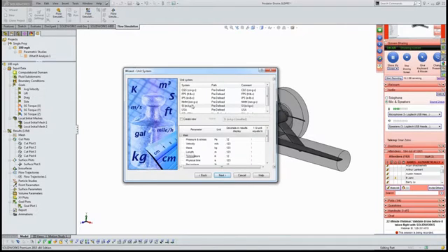Now the next thing that it asks, all right, what unit system do you want to use? And for those of us that are based here in the U.S., you know that we're very tied to our U.S. unit system. We're not a huge fan of metric. I'm not quite sure why, but that's the way it is. So I'm going to use the SI unit system, but I'm going to make a couple changes. I want to work in temperature of Fahrenheit and velocity in miles per hour.